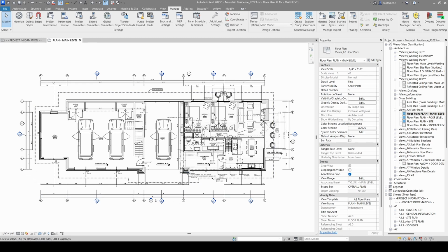And so this is actually an east elevation, but the rule of thumb is whichever cardinal direction your building's face is looking. Imagine the wall has a set of eyes. Say this north wall has a set of eyes and it's looking in that direction. If that direction is north, then it would be a north elevation.